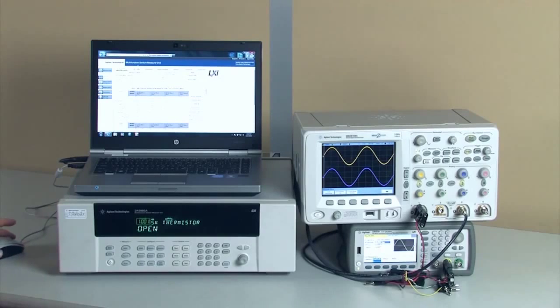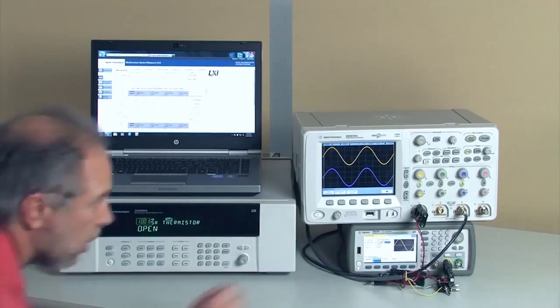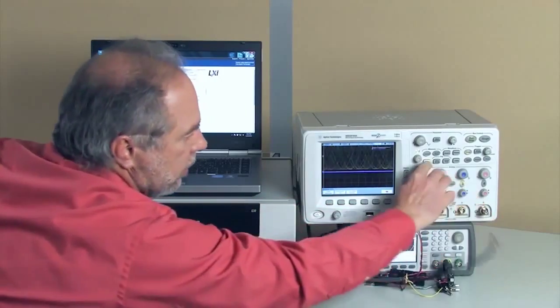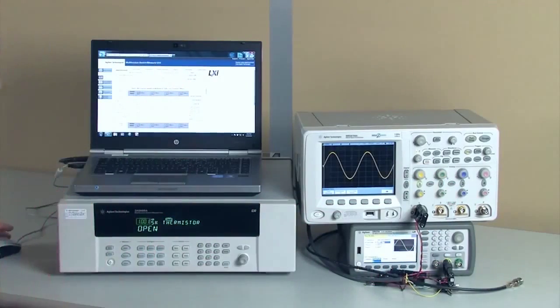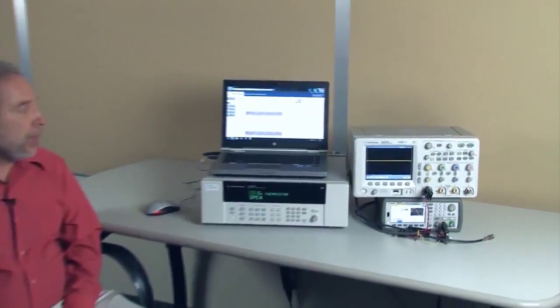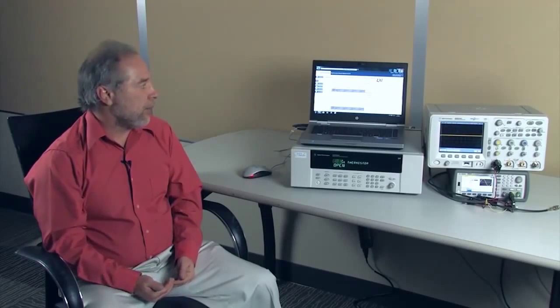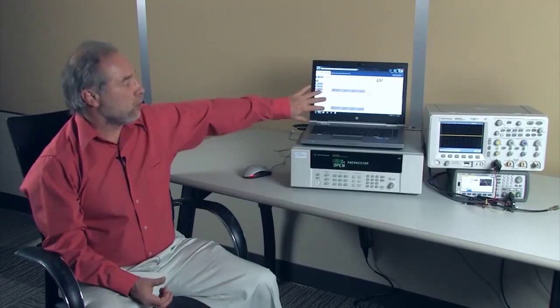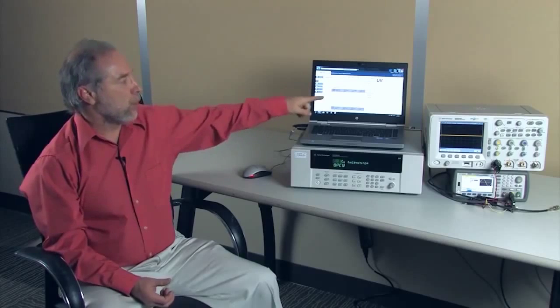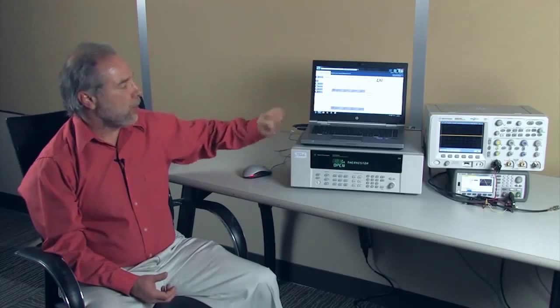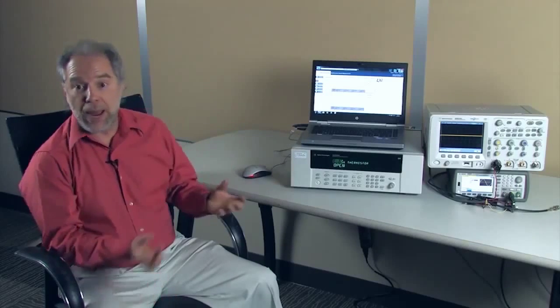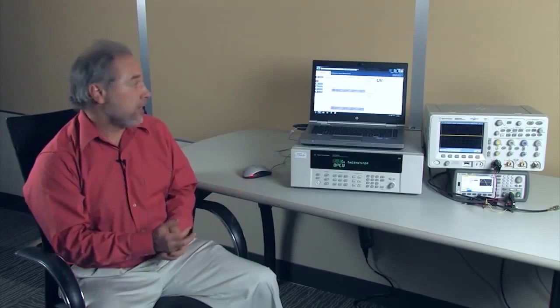Okay, I'll turn off the switch and do another auto scale, and our signal's back. Now I'm going to turn off the analog bus, and now you see the signal has been removed. You can repeat this same process with an oscilloscope, and that way you can connect any one of these 20 signals through a different bus, and then use the oscilloscope to measure any one of these 20 signals.